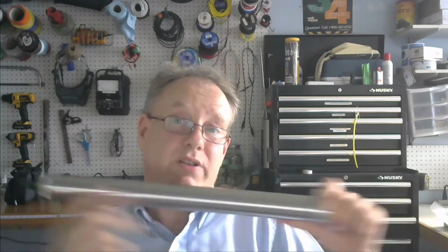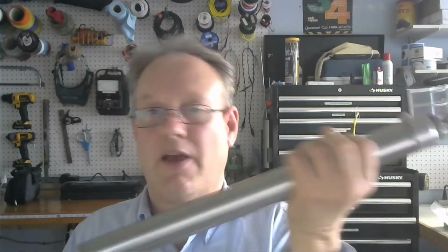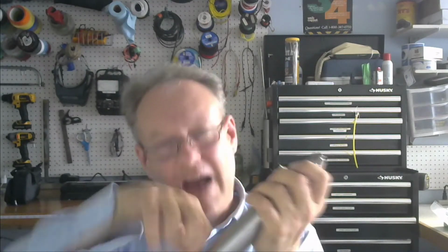And yes, to some degree, I'm losing a little bit of my force because I'm fighting, but it's very small and negligible. If you really want, you can add another couple PSI on this side. If your force is so specific, you really need to have a very accurate force, you might want to just go and actually measure that force and dial the pressure until you just get it right. Because that back force that's created from that pressure is actually going to play into that to a very small degree, but you may have been thinking about that, and it is kind of part of it, but very rarely do we actually worry about that.